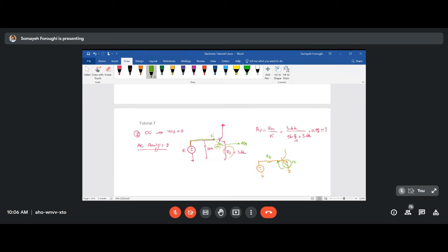Okay. The voltage at the base, though, I thought would only feel the R pi and RE times (1 plus beta). I thought it had to feel the resistance in the equivalent pi region because it was going from the voltage of the base and not the voltage of the emitter.